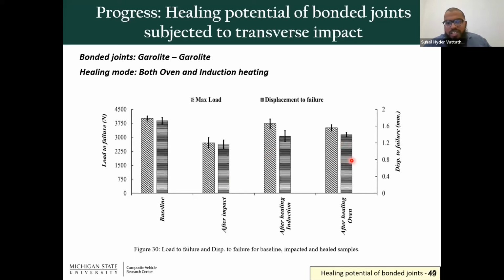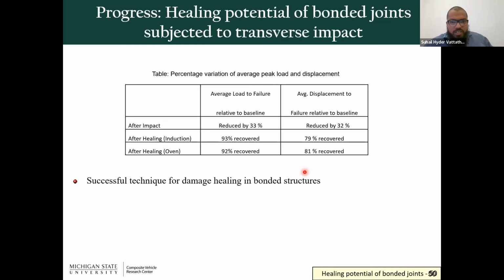So you can clearly see the lead time reduction, because that is one of the major constraints even in aerospace that we are facing. If there are some issues of repair or maintenance, it takes a lot of time for the customers to get the airplane back, because they need to make sure that the healing procedure was properly satisfied. After the healing process, nearly 92% of the strength was regained, and 81% of the displacement was regained. So it's not a 100% recovery, but still it's a decent technique.